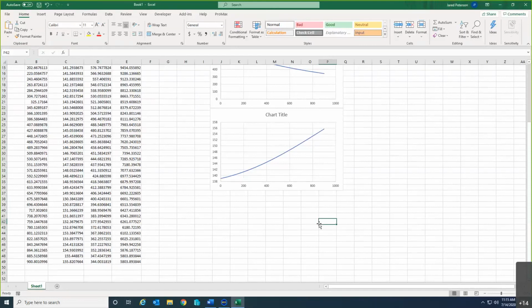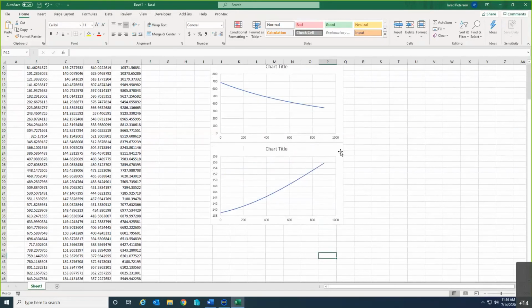I do want to point this out. It will not get hotter in all cases. Oddly enough, even with a fire case, there are some unusual systems that I've run into where you can actually cool. Now, you're not going to cool very much, and you'll only get it in the case where your valve snaps shut. For this case, because this is a fire case, we are heating.